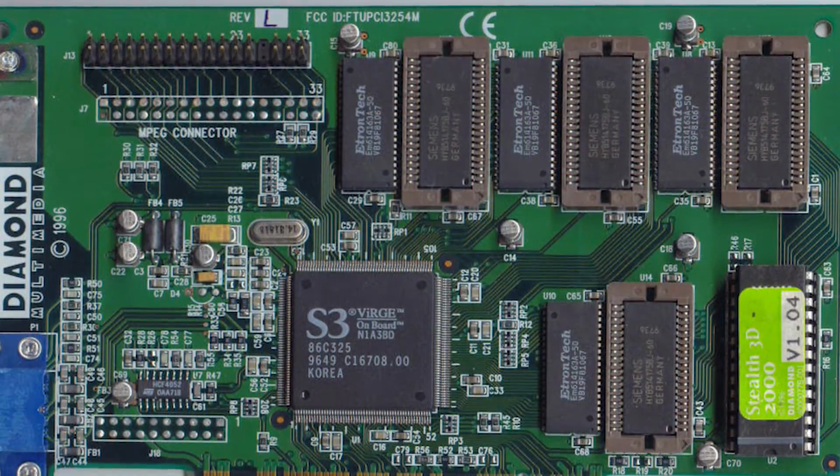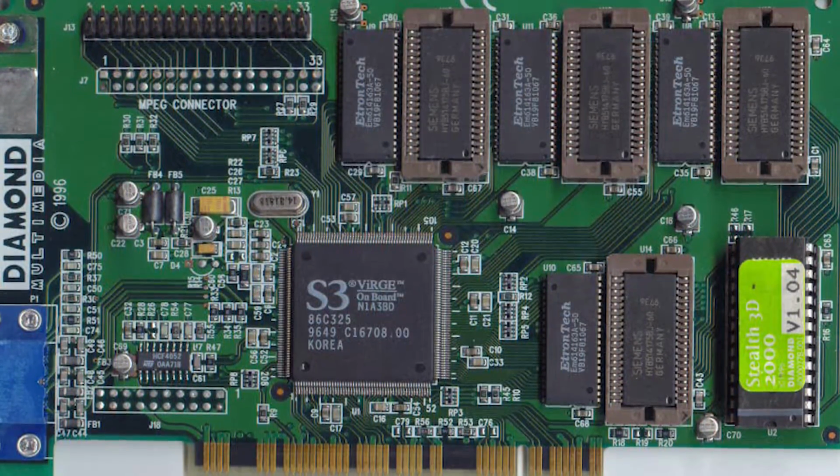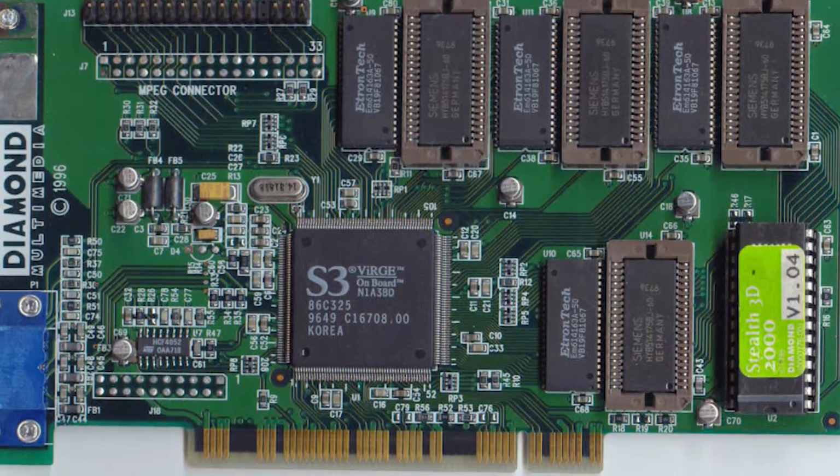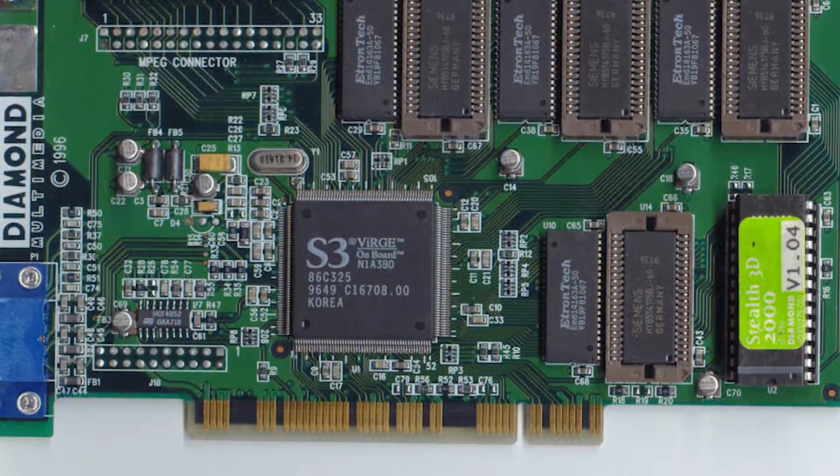VGA was a significant step up from CGA or EGA because VGA could reproduce 256 colors. The signal was still composed of both analog and digital information. Together, these were known as RGB-HV, or red, green, blue, horizontal sync, vertical sync. The digital portion of the VGA signal was used to allow the display to communicate with the video adapter. Information about supported resolutions and refresh rates could be used to ensure the computer was displaying information correctly.